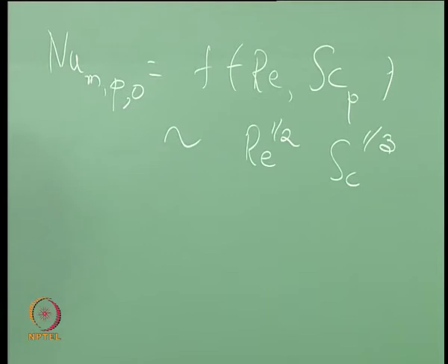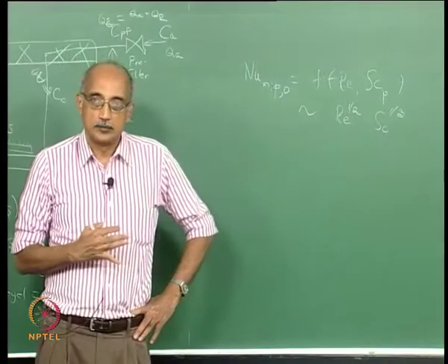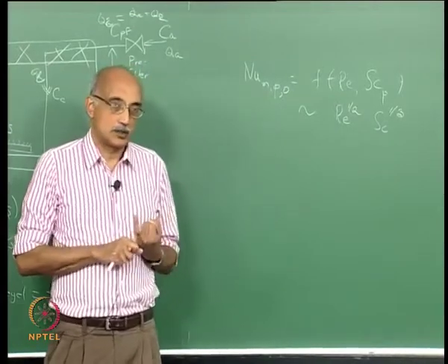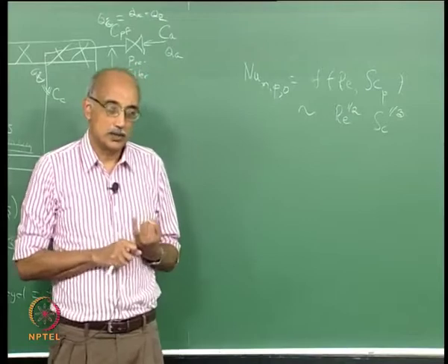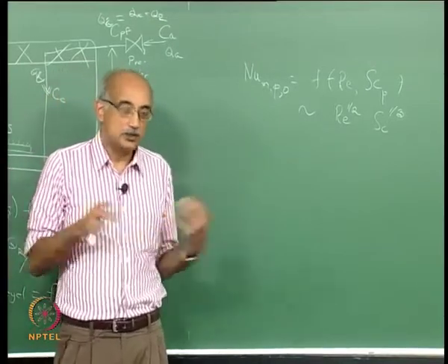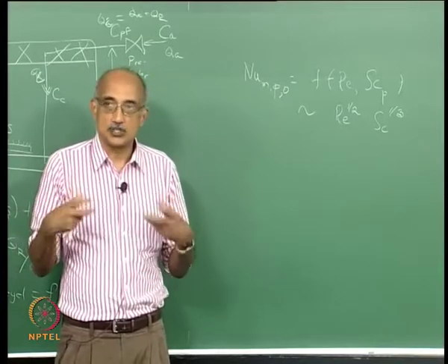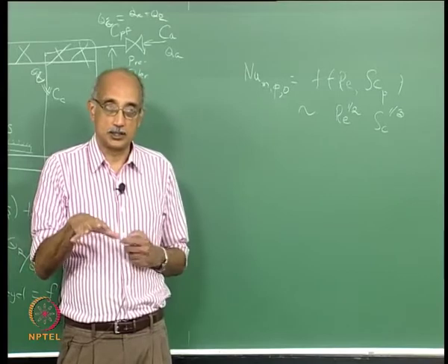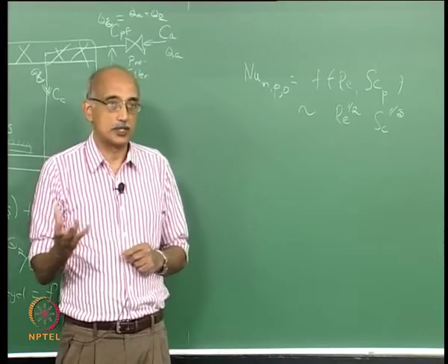But inside a clean room actually the phoretic forces are very strong, because for one thing electrostatic forces are pretty high in magnitude inside a clean room. The reason for that is that the clean room is so clean that static charges develop very easily. Low humidity conditions are especially conducive to development of charge.